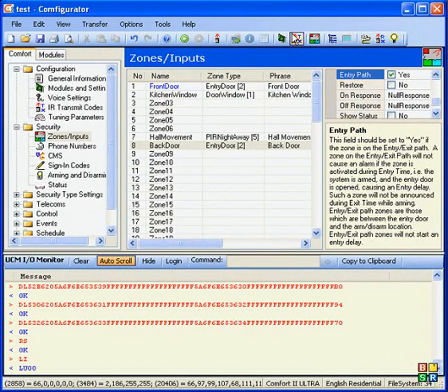So I'm going to open zone 7, hall movement. Now I'm going to open zone 8, which is the back door. Back door. Okay, so the security check tells you that you have programmed your zones and the words correctly. To end the security check, press F on your keypad. It says, thank you, goodbye.